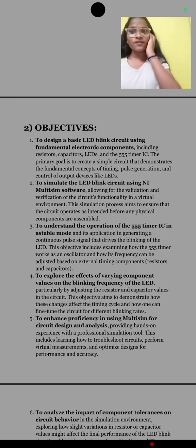To explore the effects of varying component values on the blinking frequency of the LED, particularly by adjusting the resistor and capacitor values in the circuit. This objective aims to demonstrate how these changes affect the timing cycle and how one can fine-tune the circuit for different blinking rates. To enhance proficiency in using Multisim for circuit design and analysis, providing hands-on experience with a professional